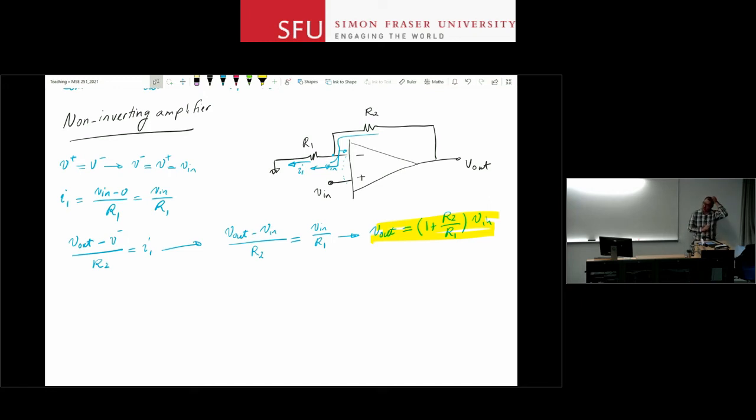Now there is another advantage to this circuit, and that's where you consider the input resistance, right? So when I look at this circuit, I'd like you to go and think about it and tell me what the input resistance of an ideal op-amp is. Convince yourself that in terms of input resistance, this circuit is superior to your inverting amplifier. In most cases, I'm not going to say in all cases. Okay. And we can check your answer during the live sessions as I mentioned before.